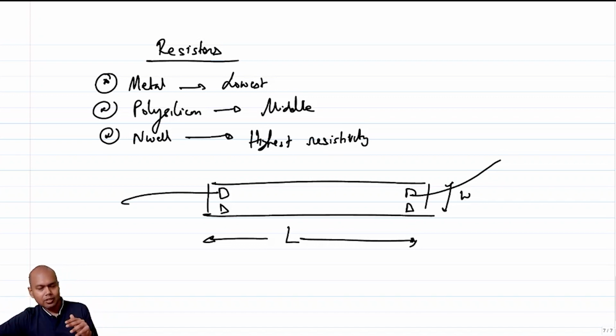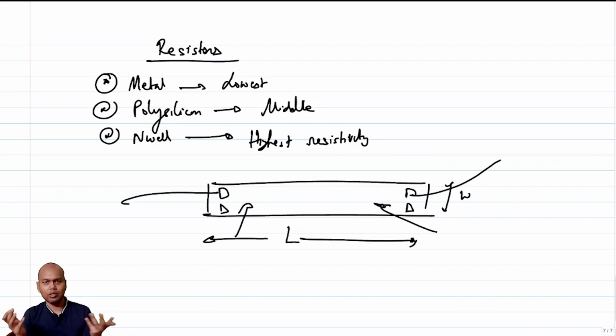then the doping concentration in a process can itself change, so that the value of the resistivity around this point, or the doping concentration of this point and doping concentration of this point, is not the same. So when the chip actually comes out, you might end up getting a slightly different value of resistors than you normally get, right?